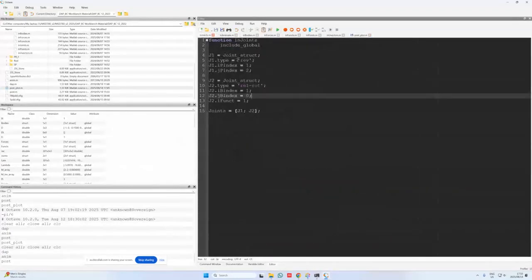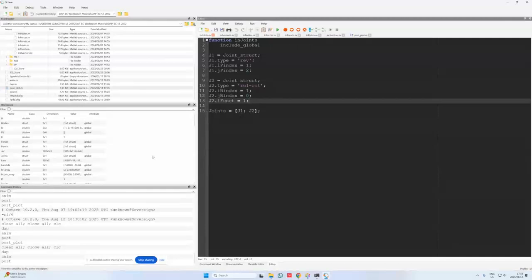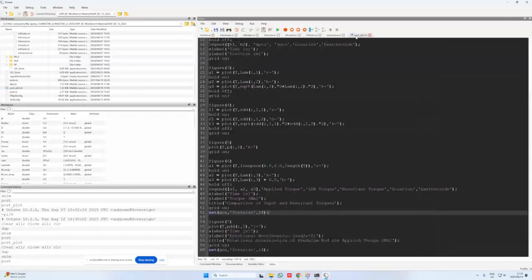If I go to in joint, I first specified the revolute joint. A revolute joint has 2 constraints associated with it, an X and a Y reaction force. So those take up the first 2 constraints of this 3, and then the relative rotation driver now imposes a torque. So this is then the second joint that I specified, but it also enforces the final driver constraint that I have in this case. So this is then the third driver constraint. And this is then also where the postplot.m figure 6 comes into play. Lagrange multiplier 3 is the torque that I specify on the system.